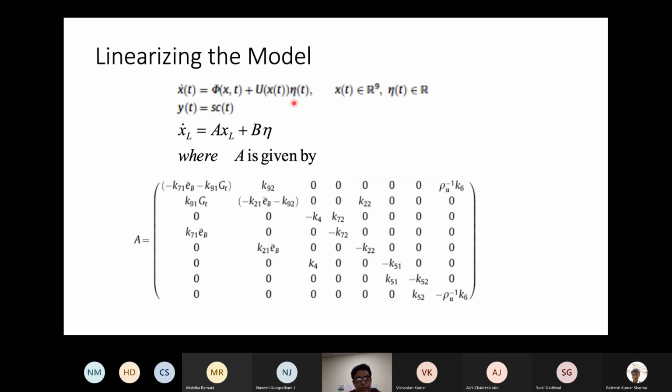Now it's going to be difficult if you have this set of equations and then try to do the analysis. One way to take care of this is to linearize it. How do you linearize? Use Taylor's theorem like I showed you earlier. You look at some condition that is useful to you, or a steady state condition, and around that point, you start differentiating everything. You take partial derivatives, evaluate at that point, and then take the linear translation of that.